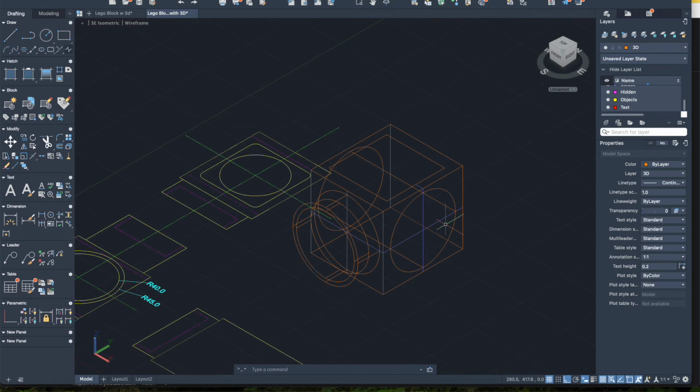And as you can see, we have to fillet the edge. So that is done a couple of ways. You can type in fillet, or you can just select it here. So when you select it, before you click on anything, you type R for radius and 10 for the degree. Okay. Now you click on a line, and hit spacebar to repeat the last command, and hit spacebar. And the last corner. Okay, so we've created that shape.